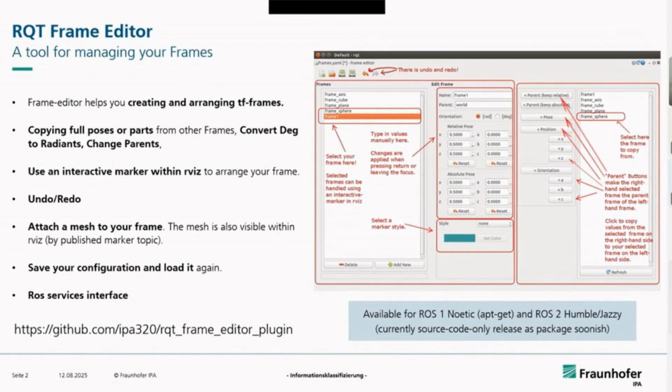It also features undo and redo functionality, and you can attach meshes to frames in order to quickly prototype your URDFs. You can save your current configuration of frames, load them again, and also run without a GUI in headless mode. Additionally, most features are exposed as ROS services, so you can integrate them into your automatic workflow and call them from other scripts.